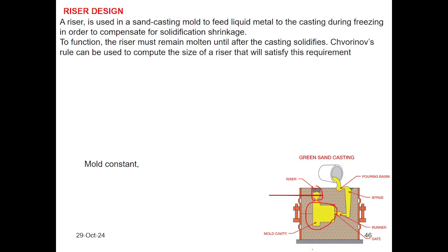You know this. The other function of a riser is that, if the porosity of the mold is not so good, while we are pouring the molten metal, the air is to leave the cavity, and while the air leaves the cavity, the molten metal fills in. Air within the cavities can leave the mold thanks to the porosity of the mold.